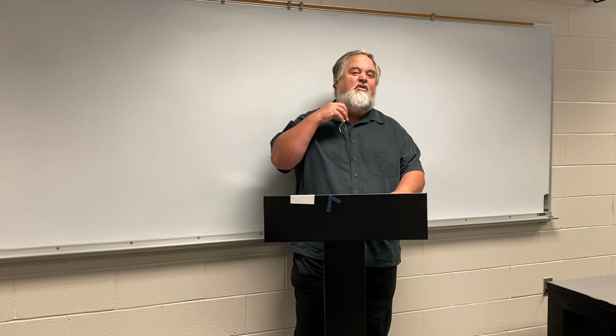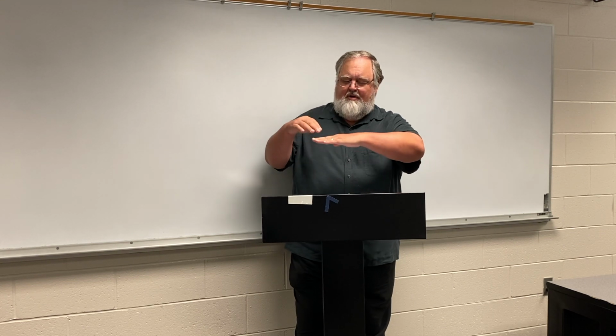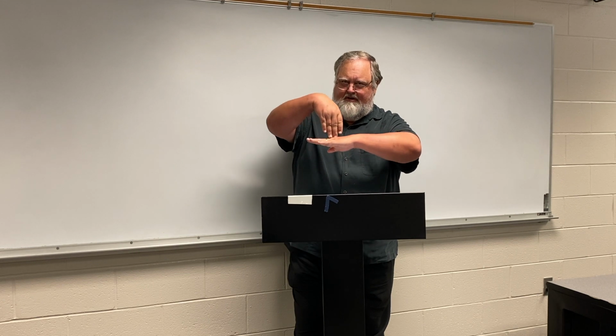So in order to understand that, you sort of have to understand this idea of a thing called stress. Now, I'm not talking about the panic you feel in life, but a stress is a force that is applied, an external force that is applied to something, yes? There are three basic stresses that we deal with in the theater. One is tension. Tension is where you take an object and pull it apart like elastic. Compression is where you take an object and push it together on either side. And shear is when you have an object and you force it from the middle of it, yes?